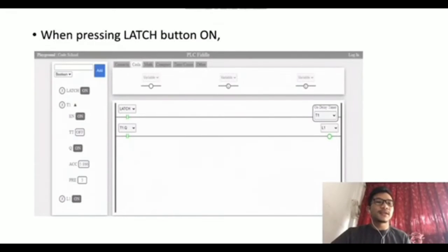We go to task number 2. In this situation, T1 is a normally open, time close contact. When the latch is closed, the T1 coil will energize with a timing period of 5 seconds delay. T1 is still open, causing L1 to still be off.